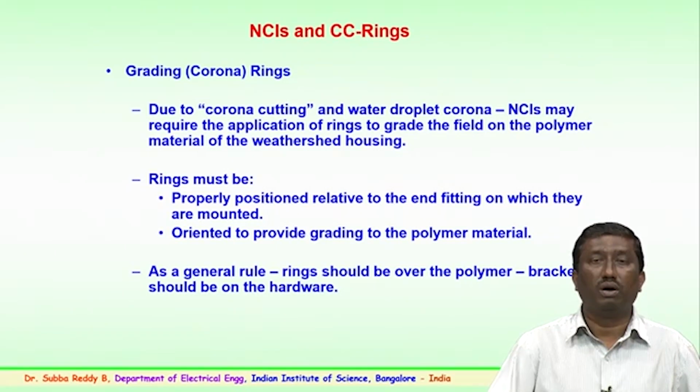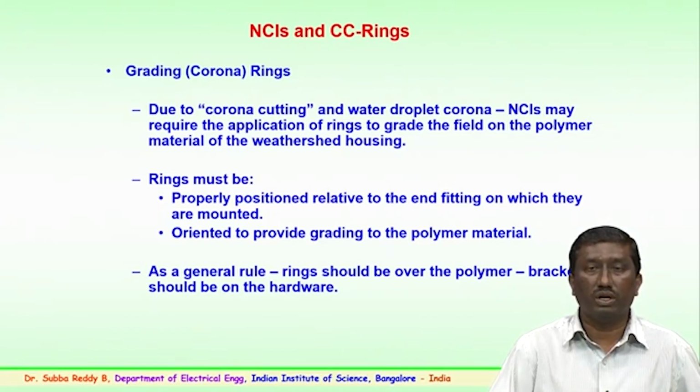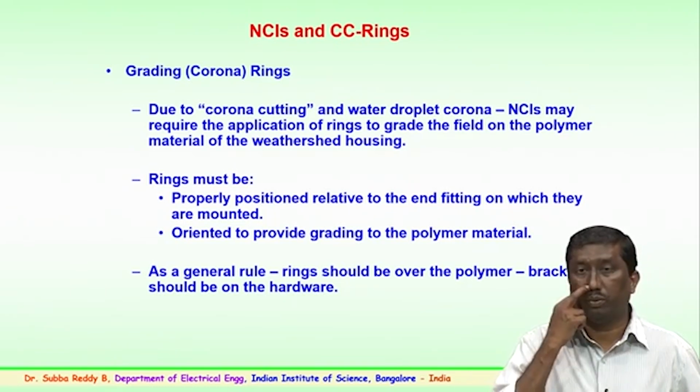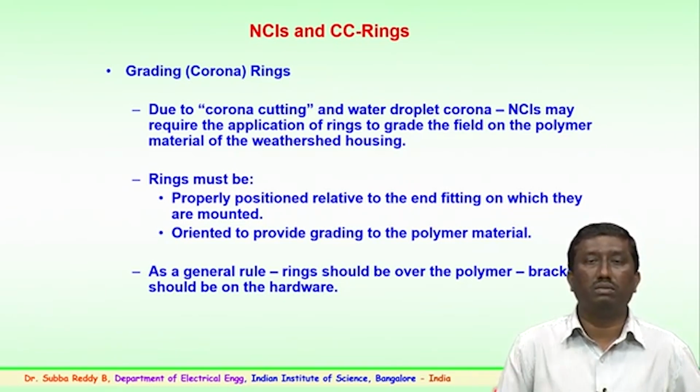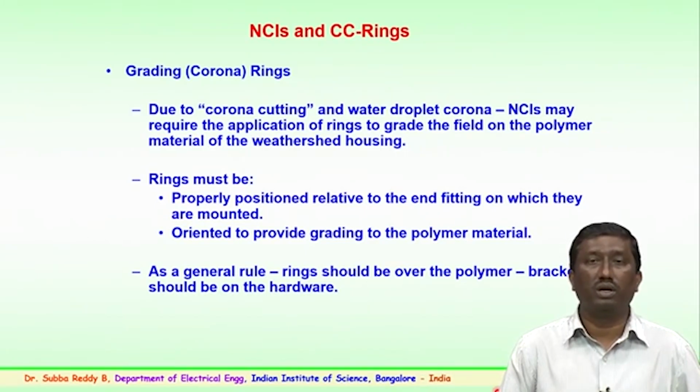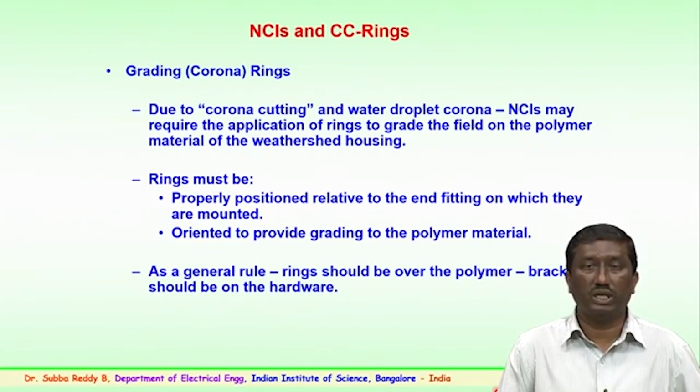The positioning of the corona control rings is equally important with the design. So, not only the design plays a role, the positioning of the corona control ring and its alignment in the string is very important, so that the end fitting on which they are mounted has to be properly mounted, else there could be a shift in the position, and this may lead to higher corona discharges which may damage the surface of the polymer sheds.